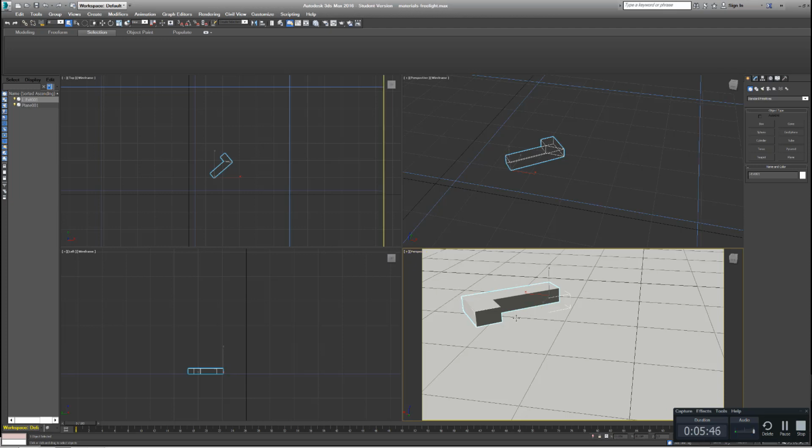So in lighting, in a scanline renderer, we're looking for a function of the physical material properties that we've set up. Right here, these are just basically stock colors, and the light that illuminates it. And in the case of 3ds Max, because we haven't created any lights, 3ds Max is using an algorithm to calculate what the light might appear to be. So it's actually completely artificial.